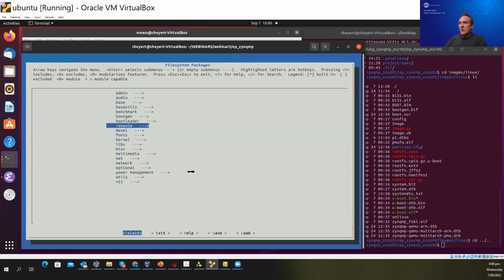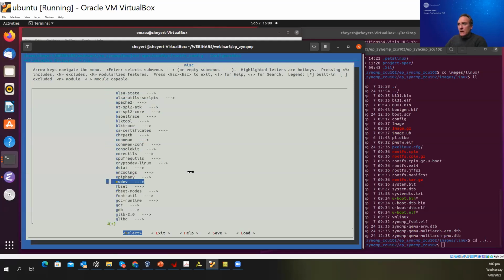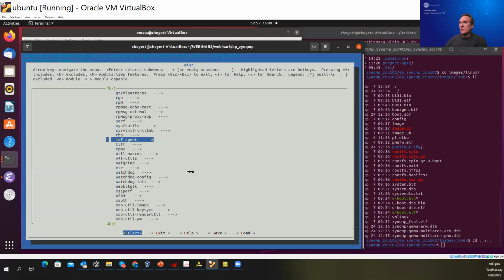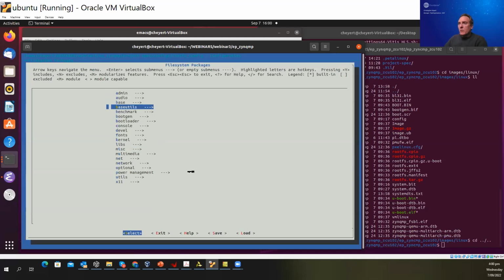So the one thing you need to check though, it's enabled by default, so I wouldn't worry about it, is the Tcf agent. So if you want to debug an application or run an application where Vitis communicates with Linux, the Linux Tcf agent needs to be enabled. But by default, it's always enabled. But again, for development, you can install make, you can add packages as you desire. So the only thing I'm really interested in at the moment is Ethernet, ETH tool, TCP dump, and maybe an application, and that's kind of it.